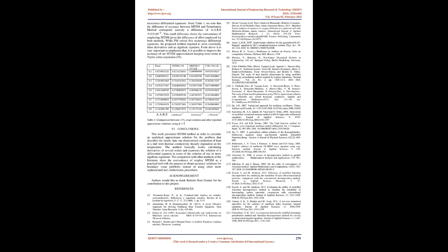This section presents the application of MTSM in the search for an approximate solution for the nonlinear ordinary differential equation that describes the steady-state one-dimensional conduction of heat in a slab with thermal conductivity linearly dependent on the temperature, equations 12 and 13. This work will follow the general idea of MTSM but will employ just one shooting parameter corresponding to the initial derivative. From this view, to calculate it will be sufficient to ensure that the MTSM solution satisfies the right boundary condition y(1) = 0. To exemplify, we will work a specific case. We will get an approximate solution for the system, 12 and 13, with good precision performing very little effort.